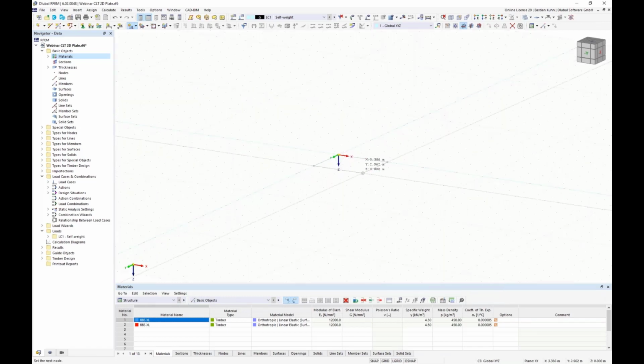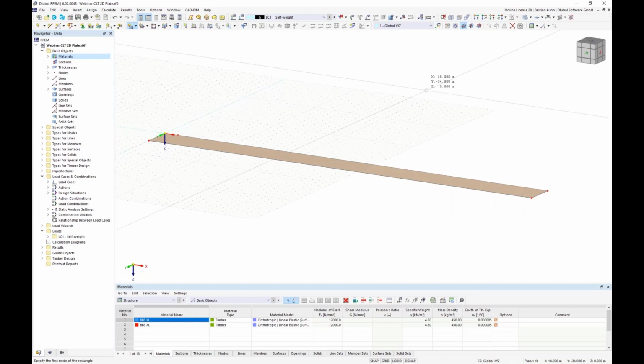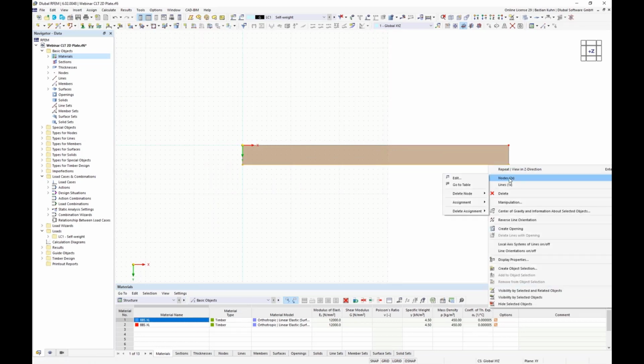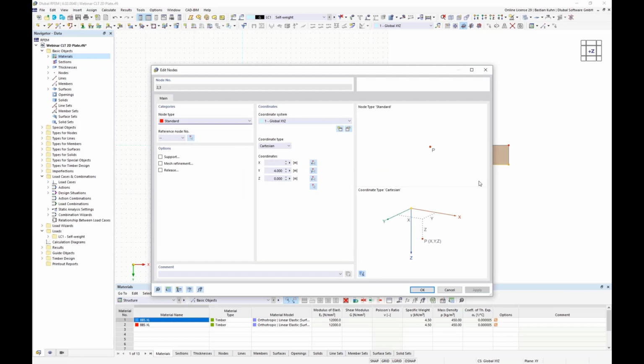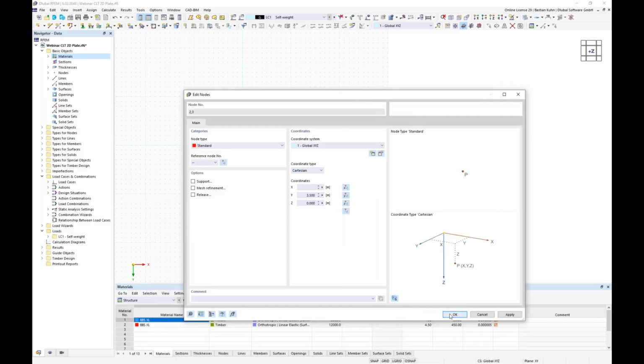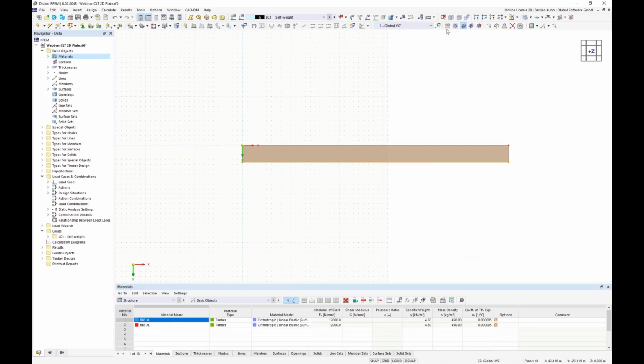Use the origin of 0, 0, and then we want to take it a width of 55 meter, and the height of each plate should be 3.5 meter. Of course, I know that it's not possible to produce a 55 meter long board, but there are options to calculate such things also stiff for the rotation. And I want to have several boards with a width of 3.5 meters in the Y direction, and that's actually where the higher force can or should be regarded.